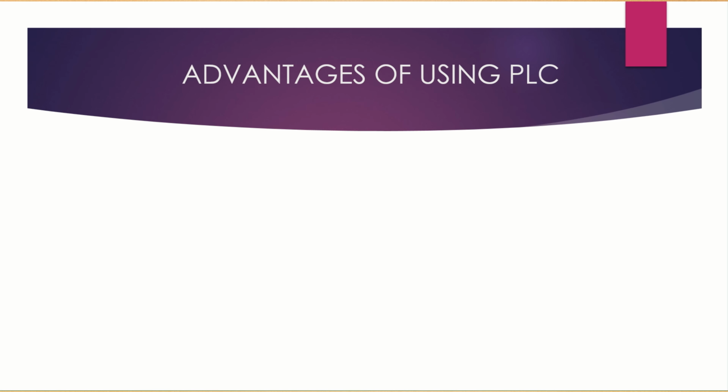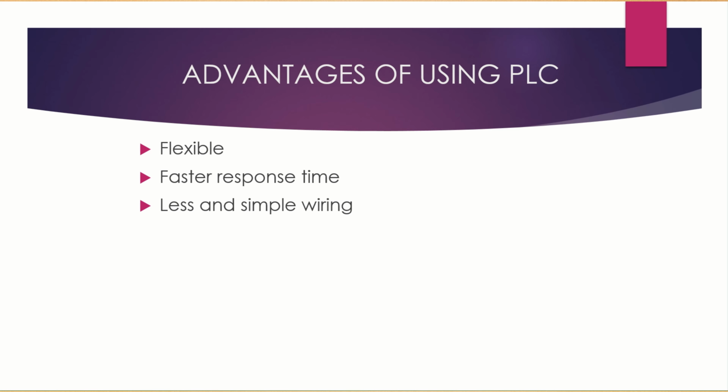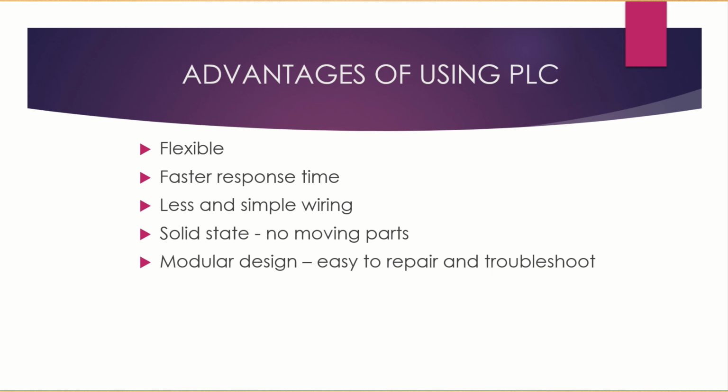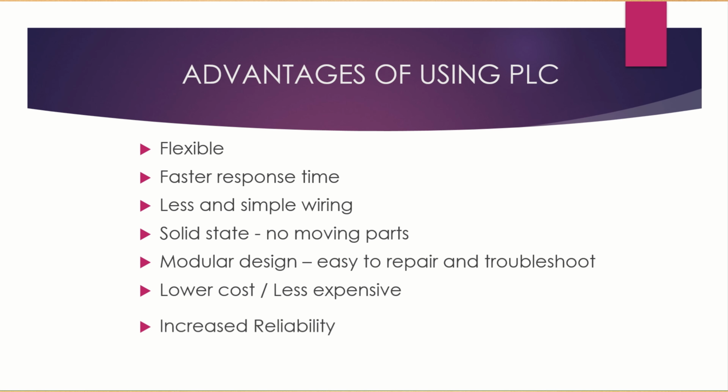Now we have the advantages of using the programmable logic controller. First, using PLC, it is more flexible. Faster response time, less and simple wiring, solid state, for there is no moving parts, modular design, it is easy to repair and troubleshoot. Also, PLC has lower costs or is less expensive.